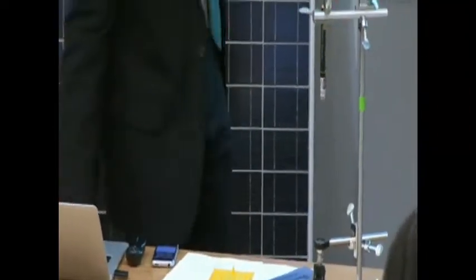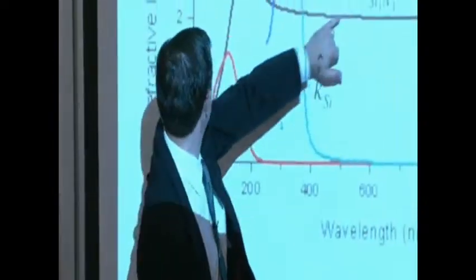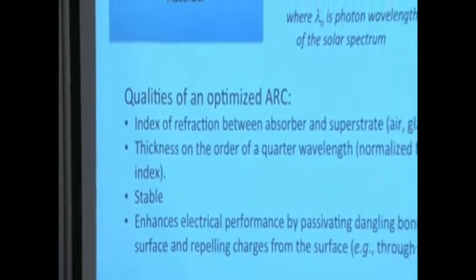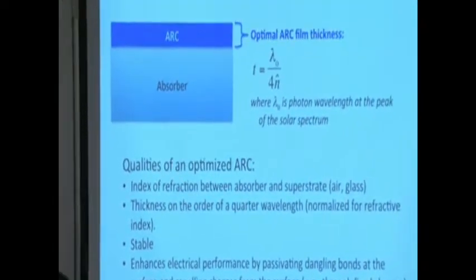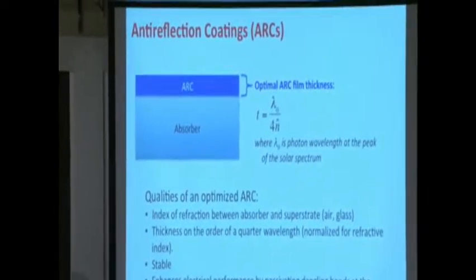and we'll give it a refractive index of, say, 2.1. Let me see if those numbers make sense. So the refractive index of silicon nitride, at somewhere around 550 nanometers. Let's call it 2, just to make our life simple. And the peak of the solar spectrum we'll again call 550 nanometers. So when we run the numbers quickly, what should that thickness be?